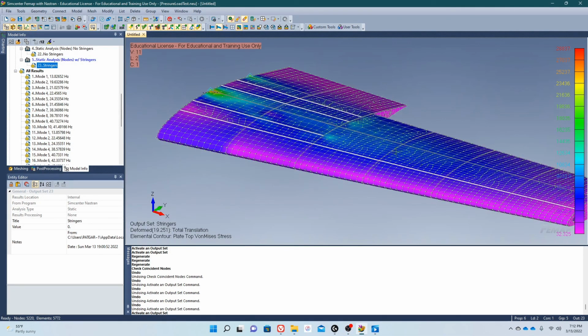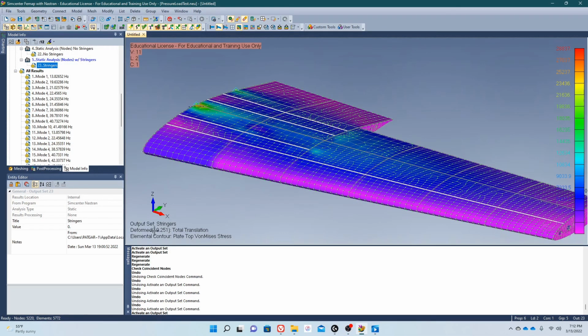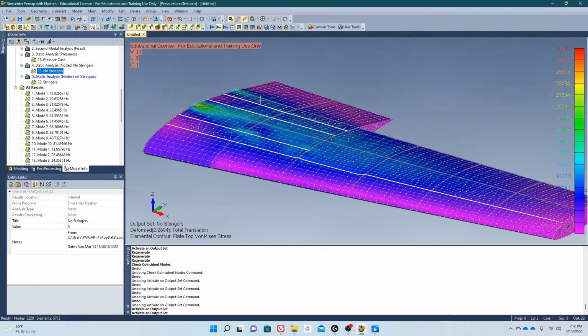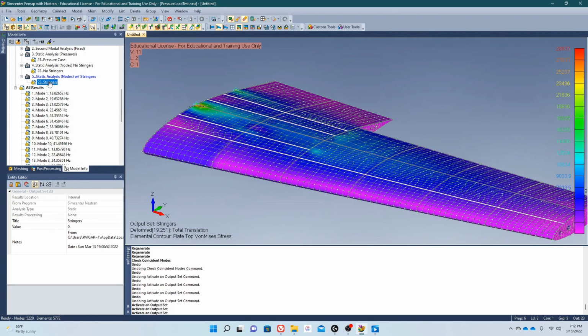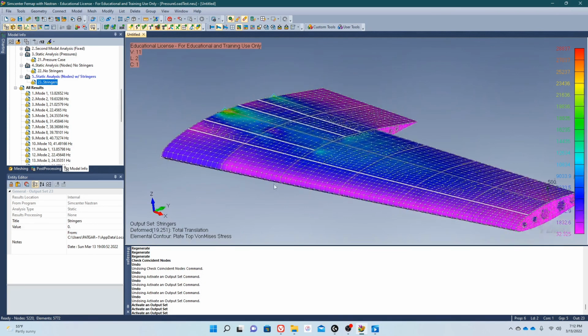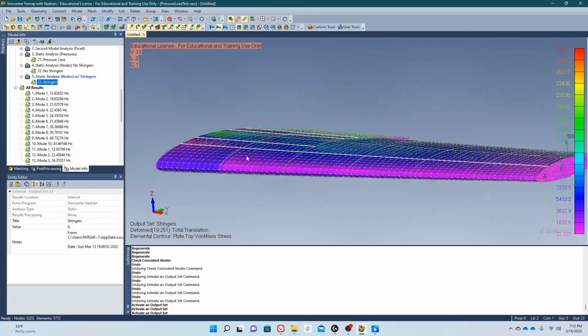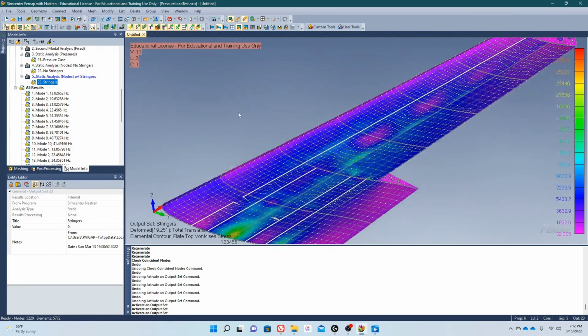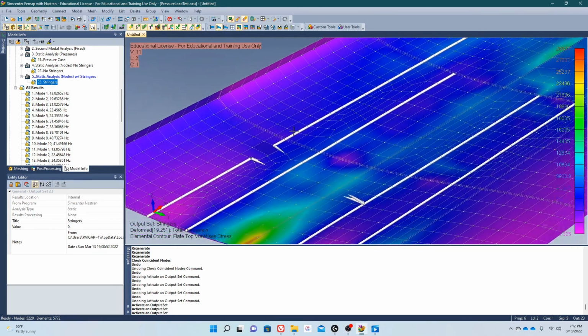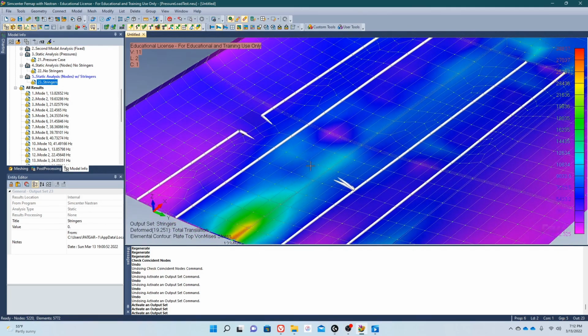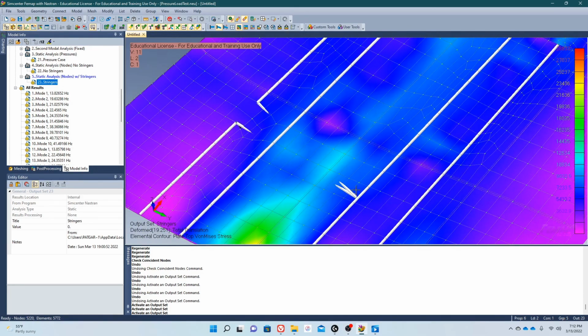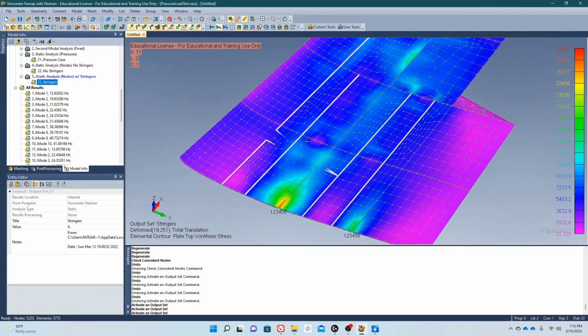So we see the stress distribution and it makes sense, but the deformation doesn't. We have 19 inches as opposed to 2 inches, which, when we're adding these stiff structures, they shouldn't be increasing our deformation by almost 10 times. And what we see if we look at the inner side is actually this displacement of this node, this rod, it's expanding more than what is realistic.